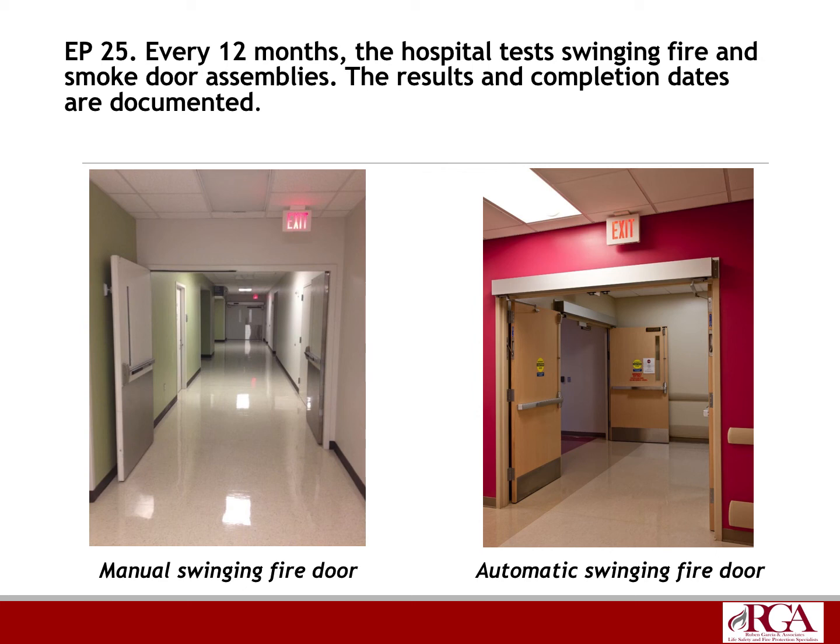That's a separate NFPA 80 check. So it's important that you get these checked thoroughly. Now, the picture on the right is your automatic swinging fire door. Now, your automatic swinging fire door, you want to try to check those in conjunction with your fire alarm vendor,